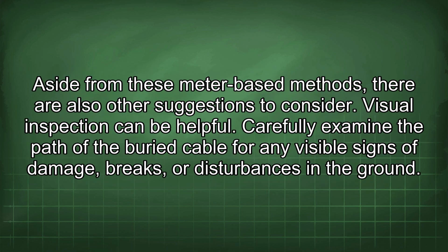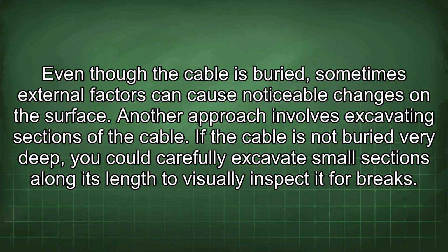Aside from these meter-based methods, there are also other suggestions to consider. Visual inspection can be helpful. Carefully examine the path of the buried cable for any visible signs of damage, breaks, or disturbances in the ground. Even though the cable is buried, sometimes external factors can cause noticeable changes on the surface.